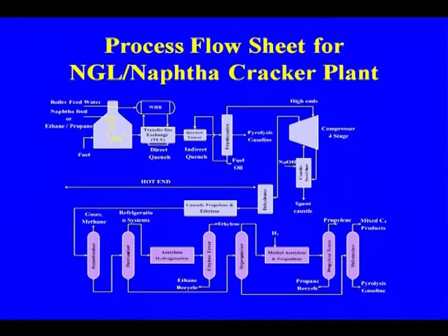These are the series of fractionating columns, and they operate at different temperatures depending upon the boiling point of the component. In the case of methane, that is around minus 165 degrees centigrade. So from the demethanizer, the product which we are getting here after the drying and the scrubbing is going to the demethanizer, where the separation takes place, and the lighter gases, may be hydrogen also, and methane are separated here.